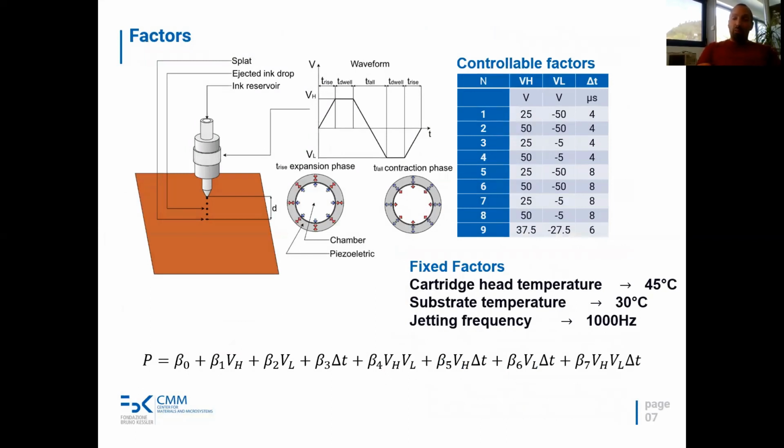So we decided to fix some factors: the cartridge head temperature at 45 degrees, the substrate temperature at 30 degrees, and the jetting frequency at 1000 Hertz.